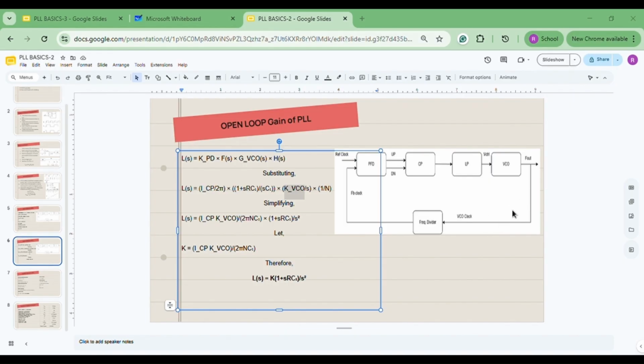And again, after this, our main VCO has two inputs, center and control. The center is basically 0.8, which is a safe margin, and the control voltage is the current from the loop filter. So after this, again, we need to convert this current into voltage, which is actually the output phase.